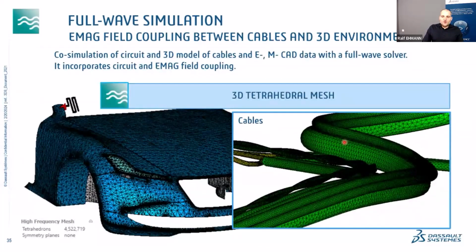Now we are merging together, or marrying together, those models. I'm saying marrying, but we are not relocating the wires to the 3D model because the positioning is already there. Once they're created, they will be at the same position where the cables were, so nothing has to be changed. Cut data, pre-mesh cut data, is already present, so we can just hit the button of the solver and run it.